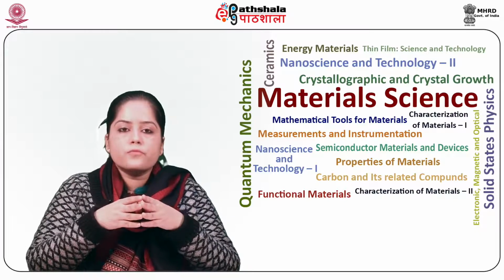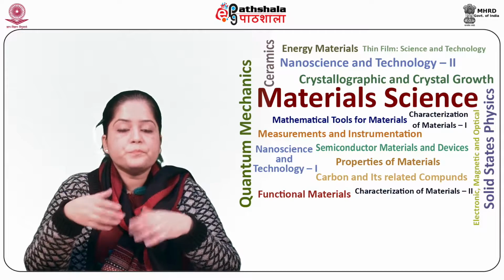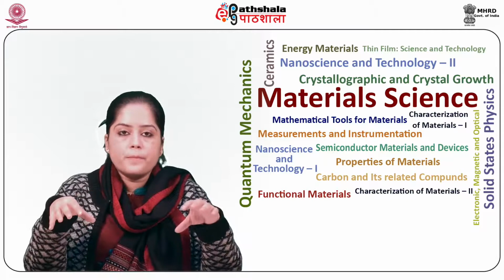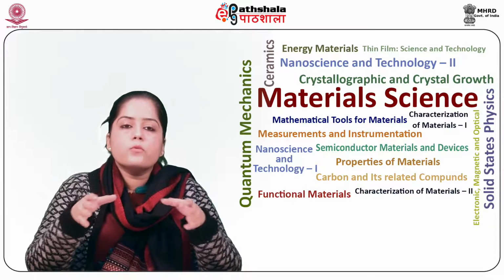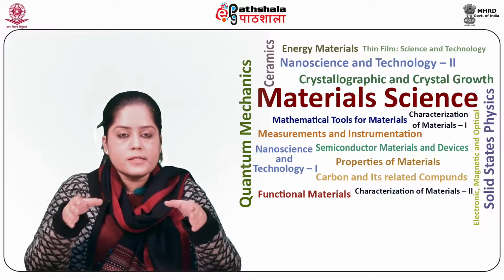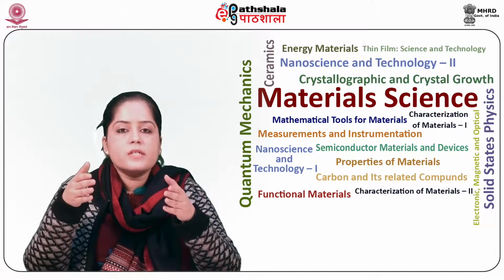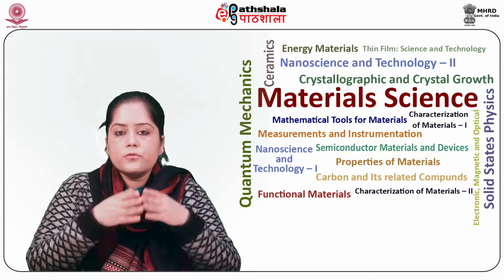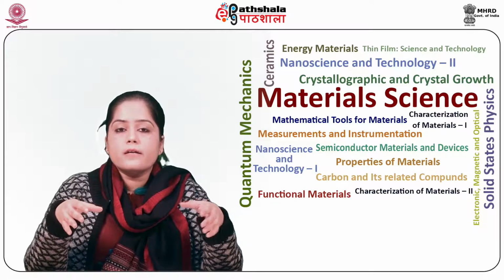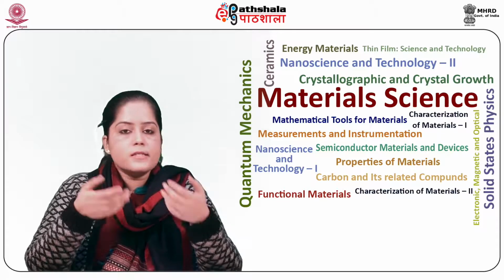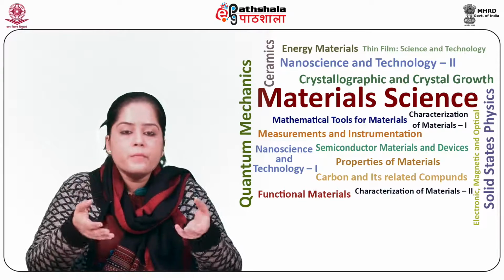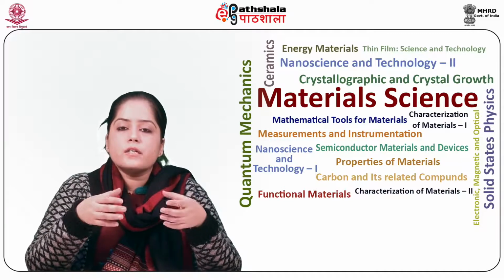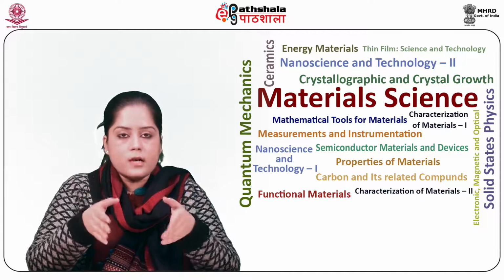Photoresist is primarily used for defining areas of interest, that is, where we want the material to be present or absent on a wafer. So the basic phenomenon includes the coating of the wafer with the photoresist, which is further subjected to selective illumination through the photomask. After the initial patterning of the photoresist, other barrier layers such as polycrystalline silicon, silicon dioxide or silicon nitride can be used as a physical mask on the chip. A photomask is constructed with chromium-covered quartz glass.